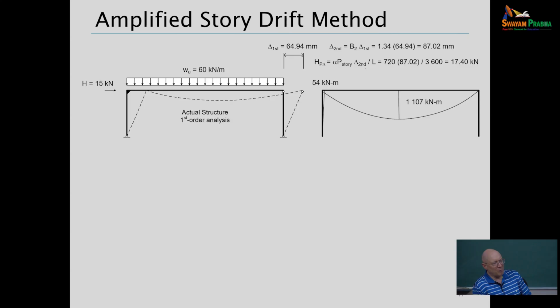So now we looked a little bit at P delta shears in a leaning column earlier. This is basically a P delta shear, or equal and opposite shear forces you can apply at the top and the bottom of the columns of your story to create the same effects as your P acting through your delta, your vertical load through the delta.